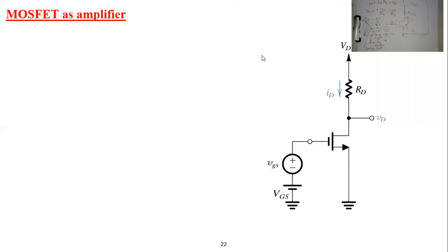Okay, so now we are back to the presentation slides, and this is the equation. This is the load line equation. Of course, this is not a standard equation, because if I add an RS here, a source resistance, it will be added to the equation. So this equation can vary. However, in all cases, this is a KVL equation across the drain-source branch. This is the standard procedure.